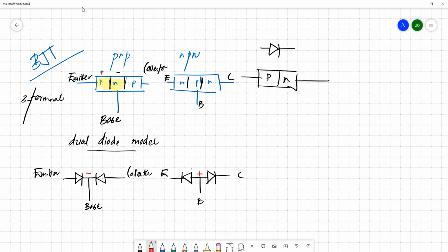So now these transistors, these bipolar junction transistors or BJTs, are basically divided into two categories, PNP and NPN. Based on this PN junction arrangement, we can model these transistors as dual diode devices. So the entire discussion is then focused again on diode operations. We convert these transistors to a kind of diode model, so then you have a comprehensive idea about how these diodes are operating. Using this knowledge, we try to understand the operation of this BJT using this dual diode model.